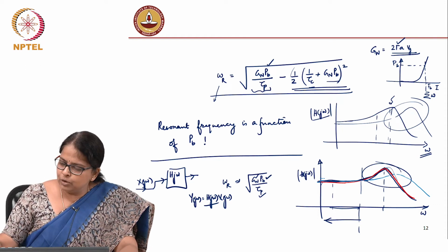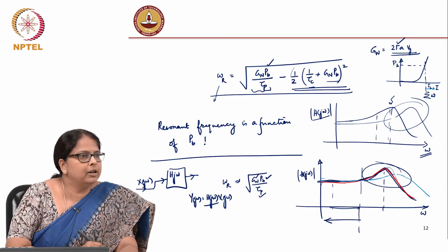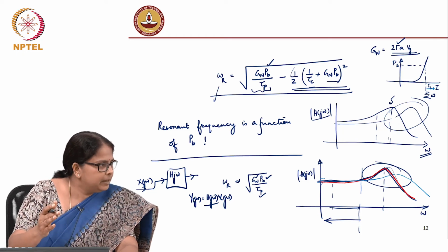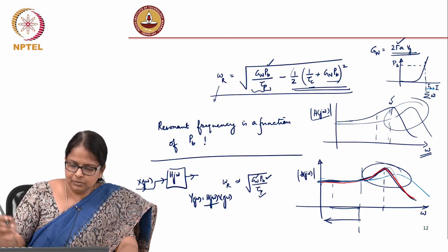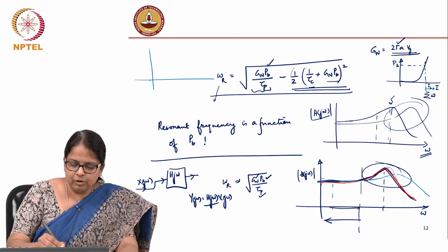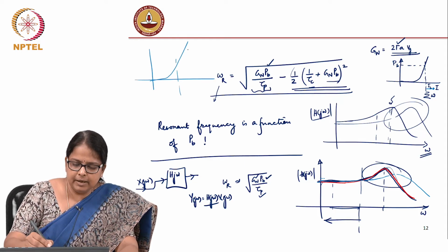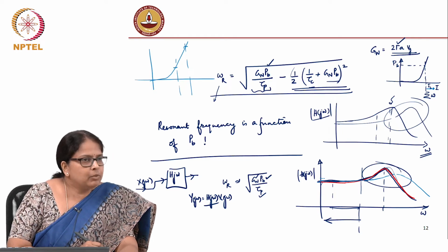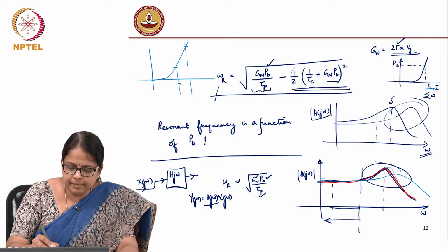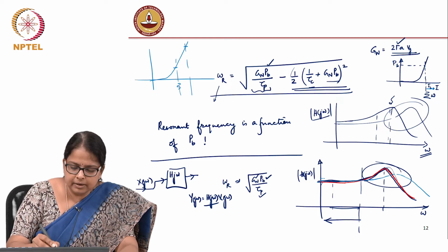But what do you lose when you go further on Pb? You will have to increase Ib. When you increase Ib, what happens? What you gain is, from this Ib to this Ib, your Pb got increased, but what do you lose? For the same depth of modulation, in terms of extinction, the average power will start increasing.